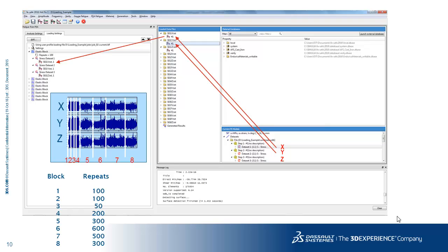And then we're going to do the same for the Y signal and Y solve, and then for the Z. Now that we brought those 3 in, FE-Safe is going to superimpose those results together for us. We'll have a single transient tensor that we've created from a steady state solve plus our time signals. And then we have now defined our first block.